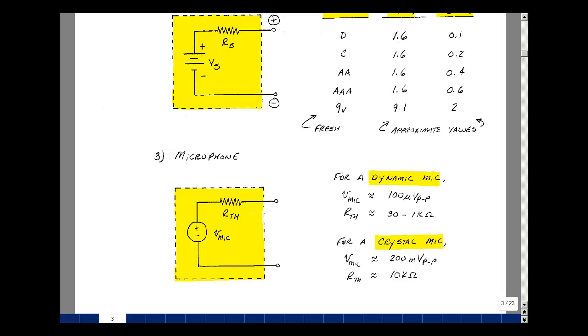There are also other types of microphones, one of which is called a crystal microphone. And this uses a piezoelectric piece of material, and it's able to generate very large voltages, in fact, significantly larger than we had with our dynamic microphone. So it can pick up sounds that are very far away. This would be the kind of microphone you'd be using maybe in a stadium trying to pick up some conversations in a huddle. But the amount of current that you can draw out of the microphone really depends on how much energy you've put into it. When you have a larger voltage, you'll have a much higher Thevenin resistance because you can't draw a lot of current from the microphone because you're just getting a sound pressure wave. Thevenin resistance for a crystal microphone is quite high. We have to worry then about input impedances of our circuit when we interconnect the microphone with, say, our amplifier. We're going to look at this in a later experiment. Let's next take a look at measuring Thevenin resistance.